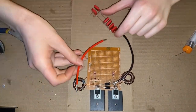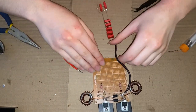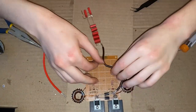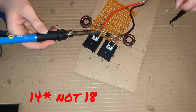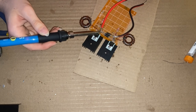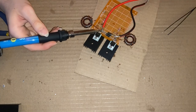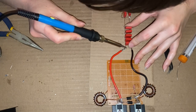The reason I connected my capacitor bank to each drain of the MOSFET using wires is because they can't be connected to the board or else they'll be damaged by the heat. The wires I use to connect them are 18 American gauge wires, and the wires I use for the inductors are 18 American gauge enamel copper magnet wire. I used 20 turns on each to get an inductance of 200 microhenry as I calculated using the inductance factor that was given on the datasheet of the ferrite core.